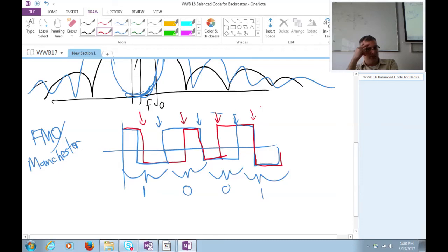So as a result, you had to make signals that had a nice guaranteed transition at regular intervals, because your signal wasn't just providing information, it was also providing the clock that you'd need to decode and logically operate on the signal. So if you imagine you were a receiver receiving one of these signals, you say, well, there's going to be a guaranteed transition every other coded data bit. So all I have to do is look for that and keep time with that transition, and I can recover the clock in that regard.